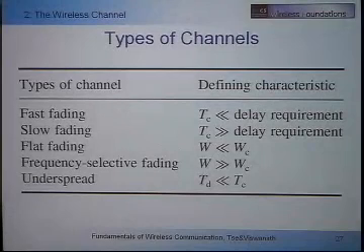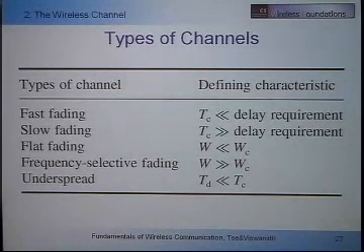So you can ask the question, why do I make this definition? Of course, I am standing here on the stage, I can make whatever definition I want. However, it should make some sense, right? So why does it make sense? If you think about it, first of all, is slow fading good or fast fading good? Or let me ask you another question. Is flat fading good or frequency selective fading good? In other words, if you have a choice, you can choose what channel you are communicating over. Would you prefer a flat or frequency selective channel? Frequency selective fading channel, right?